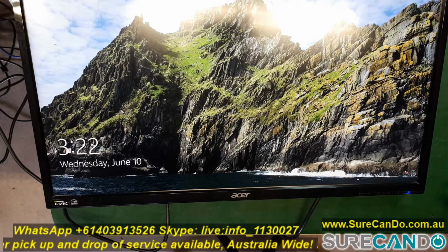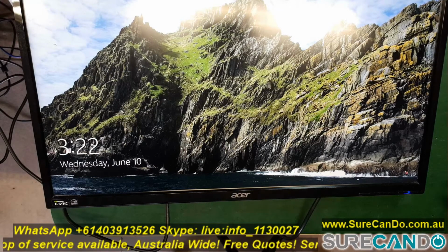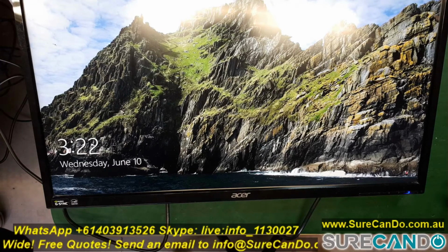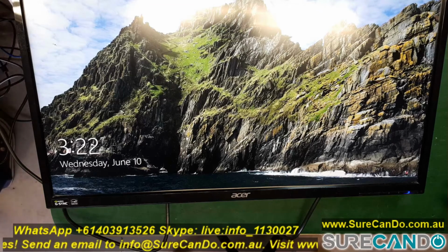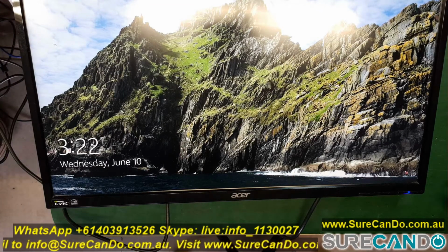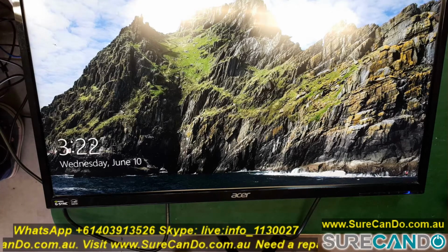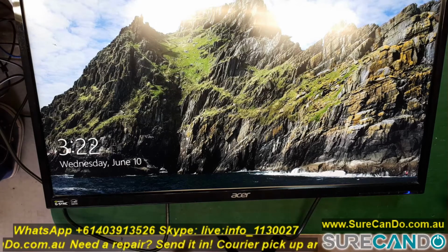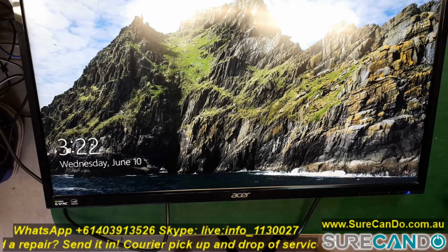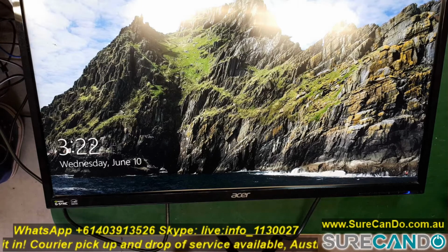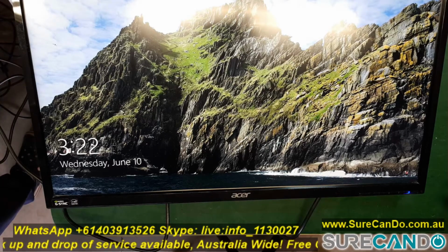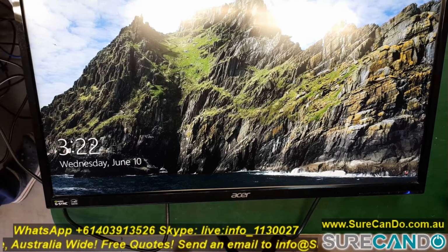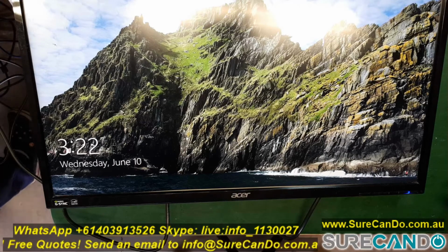Now I've had a Google search on this issue, and apparently it's very common on gaming monitors with high hertz, where people have been going crazy looking for solutions for a few years now actually. Some have found the solution, some are using adapters, like instead of DisplayPort directly, they use an HDMI to DisplayPort adapter, or they try different cables like certified, non-certified, longer, shorter, rollback graphic drivers, all kinds of things. Really weird, and there are really mixed results. There is no one solution that fits all.